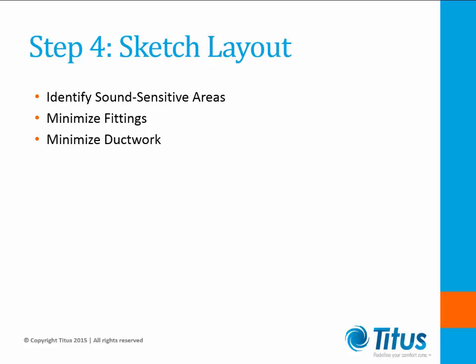Use exposed ceiling areas and low structure or high ceiling areas when possible. When sketching out the one-line ductwork, minimize fittings. Fittings increase both cost and sound of the duct system. Avoid close-coupled fittings as duct pressure losses increase dramatically in these cases.